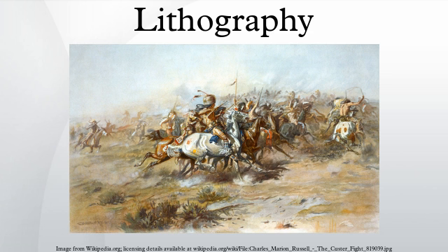The plate is affixed to a cylinder on a printing press. Dampening rollers apply water, which covers the blank portions of the plate but is repelled by the emulsion of the image area. Hydrophobic ink, which is repelled by the water and only adheres to the emulsion of the image area, is then applied by the inking rollers. If this image were transferred directly to paper, it would create a mirror-type image and the paper would become too wet. Instead, the plate rolls against a cylinder covered with a rubber blanket, which squeezes away the water, picks up the ink and transfers it to the paper with uniform pressure.